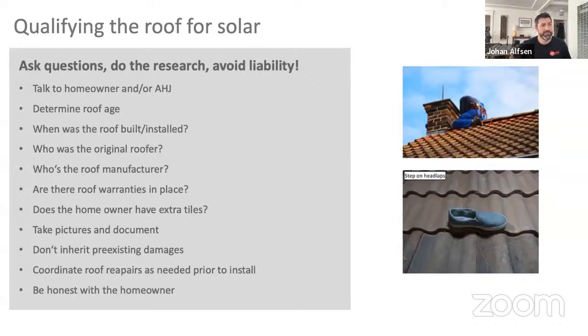So a couple things I've been doing in that K2 Pro training program is talking about qualifying the roof. So this is extremely important on tile. And I always compare this to walking around a rental car, right? You don't want to inherit roof leaks. So talk to the homeowner and the HJ and get as much information on that roof and do your research and your investigation.